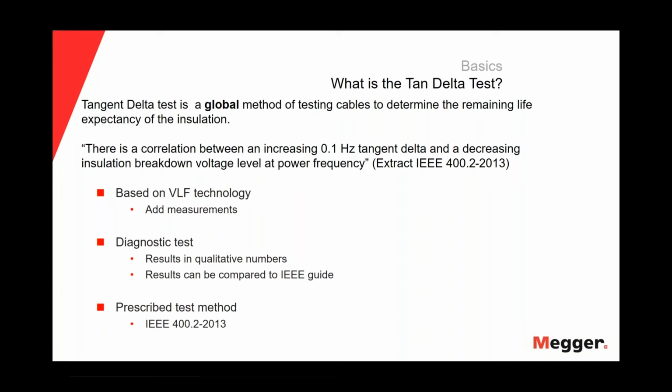That is something that we know. So the tan delta test is based on VLF technology, is a diagnostic test that results in qualitative numbers, and we also can compare the values of the tan delta with the IEEE guide, and of course the tan delta is a prescribed test method by the IEEE 400.2.